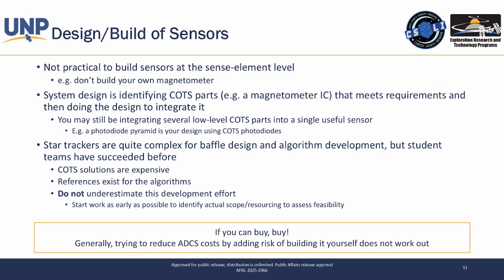What was your second question? Just about during eclipse, you had said there were some other options. If you chose to not go with a star tracker, what would you use? It depends on how accurate you need to be. This is one of the reasons why I use a rate gyro. If you know where you were pointed, between sun and Earth's magnetic field, and then you go into eclipse, you will keep using Earth's magnetic field and the rate gyro to essentially propagate your motion on the backside. So you may build up error over time. You can make it not that large, probably a couple of extra degrees. The star tracker will keep you accurate the entire time, so long as it's not blinded.